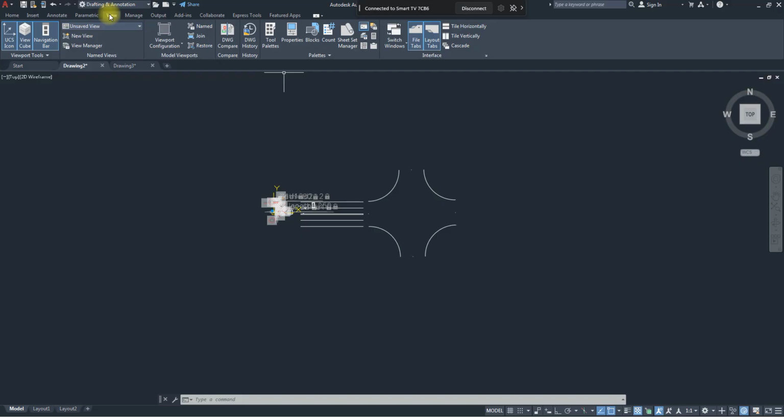If you notice, for tool palettes, you just have them as disciplines: mechanical, electrical, architecture. But for the Design Center, inside each of those disciplines, you can now have, say, kitchen utensils, office stuff. You understand? So how we do that is, to bring it, you can either use the shortcut DC for Design Center, or you can come to this View tab, the same place where you brought the tool palettes. If you come to the right-hand side, this is the icon. You don't see the name, but if you bring your mouse, you are going to see Design Center.